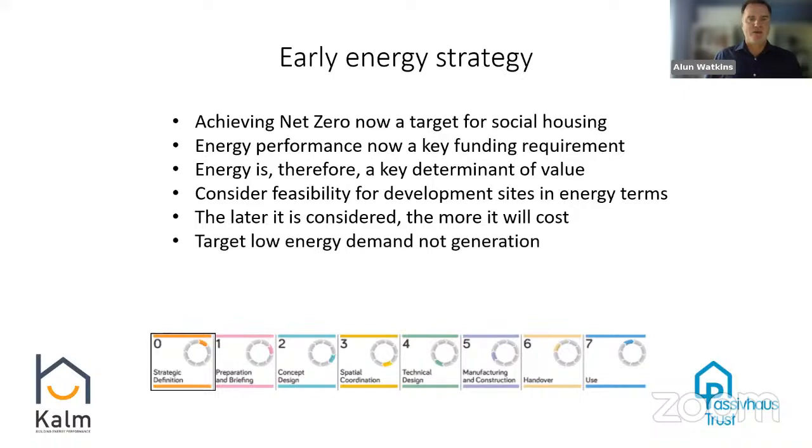We need to target low energy demand, not generation. This is not about throwing photovoltaics at buildings. Typically, the roofs aren't big enough to actually make a meaningful dent in their energy demand. We have to think about lowering that energy demand, particularly with regards to space heating, right from the outset. So we need to work with physics rather than against it.